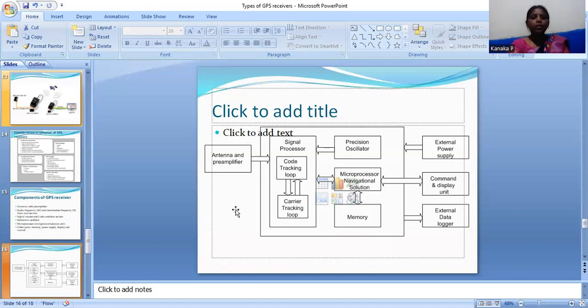So next one is the microprocessor. The microprocessor included in the total station is used for reduction of observed data. Next one is the electronic theodolite. Nowadays most manufacturers produce electronic theodolites covering the range offered by the optical equivalent, but at less cost. The electronic theodolite displays horizontal and vertical angles to 0.1 seconds with a standard division of 0.5 seconds. The common features provided in the theodolite cater for tilting of the vertical axis.